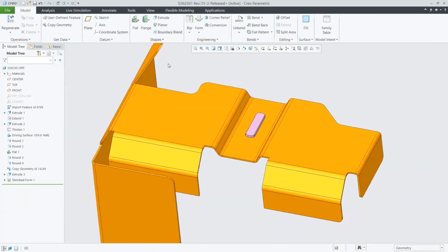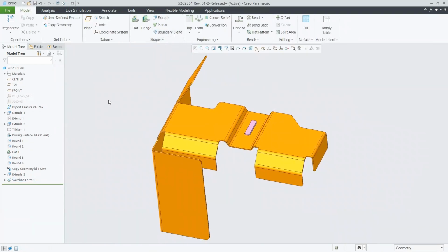So now what we've done is, using the reference geometry of the boss in the middle, our bracket will be lowered and relocated based on where the boss is on the battery of the NX design. So the idea here is we're basing our design off of the battery design that we're buying. And this is huge because it's very, very rare that someone's doing everything in-house. You need to be able to work with designs for parts that you're buying from different vendors and suppliers that directly impact the parts that you're designing yourself.